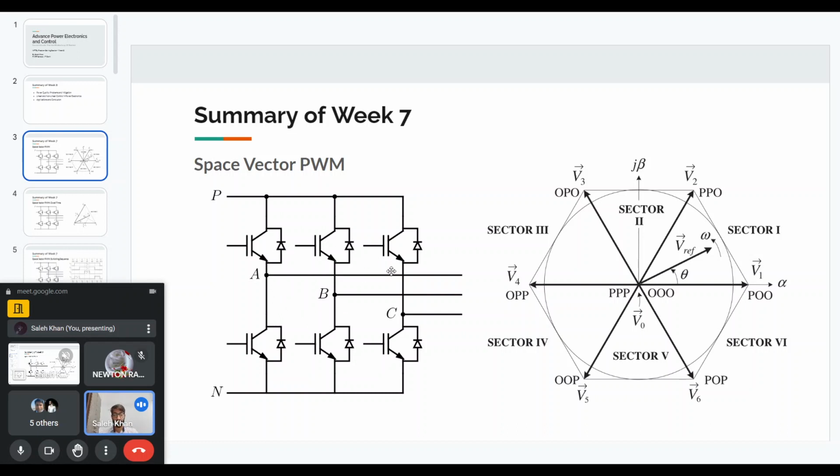And then we can now come to the space vector diagram. We start from the origin. If all the bottom switches are on, then we are at the origin. So 000 means we are at the origin. Now, if any of the phase legs' switches in any of the legs is on, then we will move to the right, or in the positive direction of that axis.